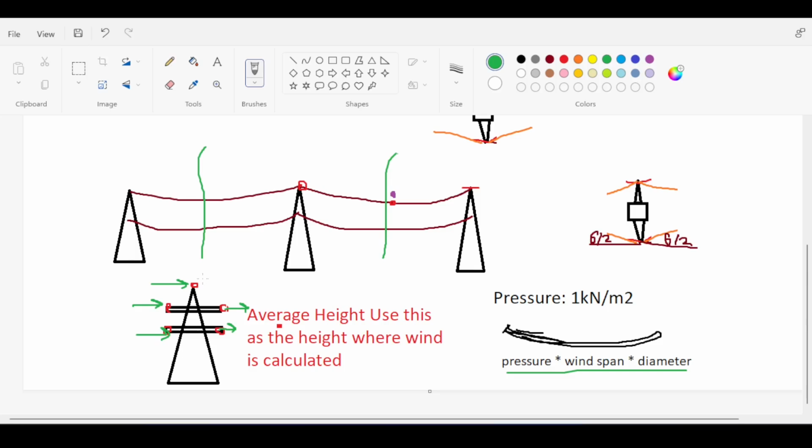Now, this is not enough, because according to the ASCE code, depending on your local codes, you might need to calculate a wind load at a 30 degree angle or something. Of course, in that case, you need to cosine and sine this load to find the load on the tower. That's not everything. So the wind load seems to be okay-ish. There's not much to say here.